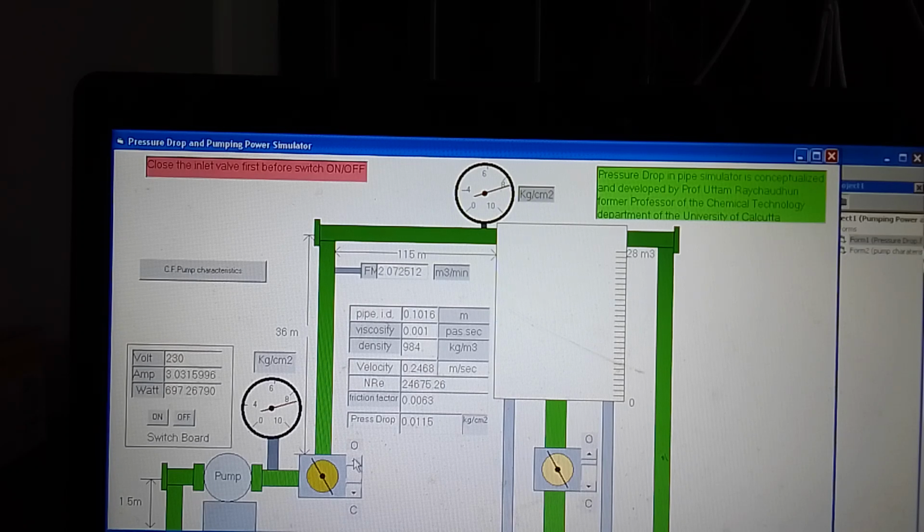Usually we maintain a constant flow rate at a constant pressure, and whenever it is required to maintain different flow rates, we have to change the opening of the valve. The pressure at the discharge of the pump will gradually come down, and the flow rate will increase and continue to grow. Maximum power consumption is also a factor. Too much power consumption may damage the motor.